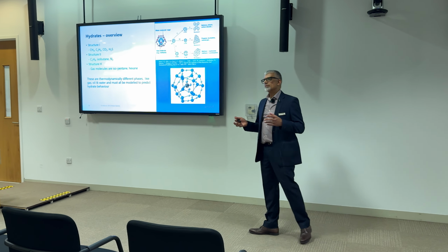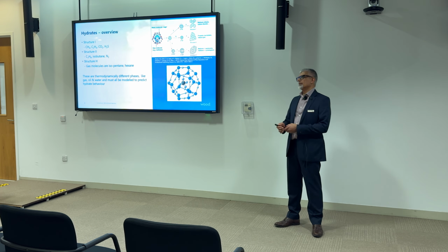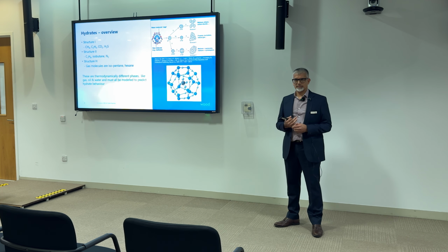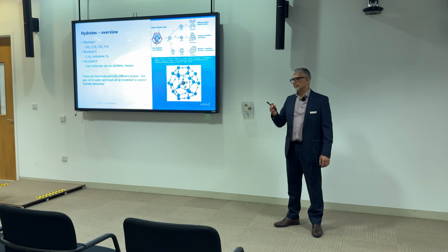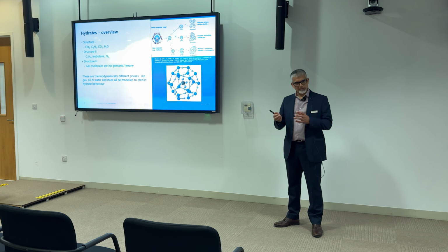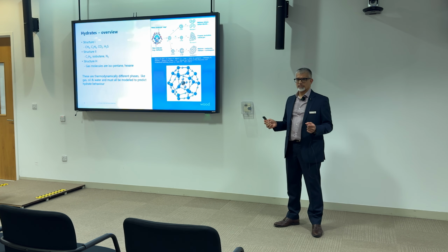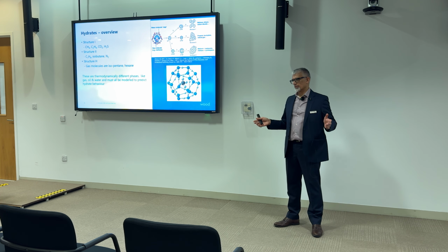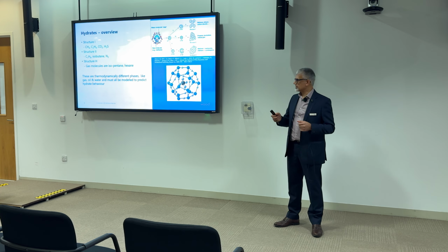Okay, so hydrates are a very strange phenomenon. It looks like ice. Now, normally you'd say, if my temperature is above 0 degrees, ice doesn't exist. However, hydrates can exist at 5 degrees, 10 degrees, 15 degrees. Suddenly, you have a system where ice is formed, where ice should not be possible. It forms, it blocks the pipeline. Once it blocks the pipeline, you've stopped production. Then the problem is, how do you dissolve this ice? Now, it's not really ice, it's a structure that behaves like ice.